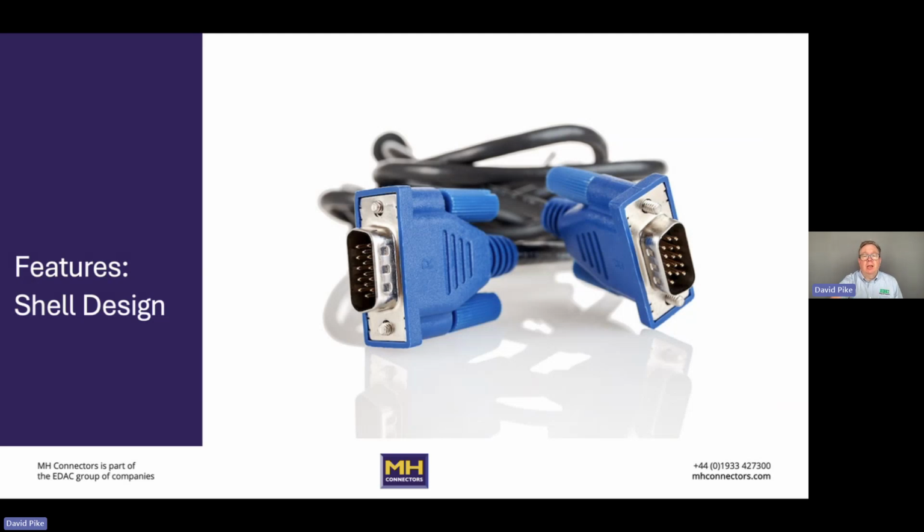This picture shows very clearly the design of the outside of the shell here. These three little dimples here, these allow a good electrical contact between the male half and the female half of the connector, providing electrical shielding around the connector itself, where we live in an environment that's awash with electromagnetic radiation. Some of it's intentional, some of it's not. And we need to protect the signals that are going through these connectors from interference from that electromagnetic radiation. And the D sub still does that very, very well.